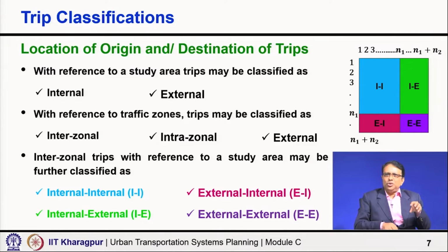Interzonal, one zone to another zone, getting produced in zone 2 going to zone 3, outside zone 2 or outside the zone where it is actually produced, that is interzonal. The other is external, where nothing is happening within this zone. So, maybe you can also consider the bigger boundary, if I consider the zone boundary. Any trips which have nothing to do with this study area is external.